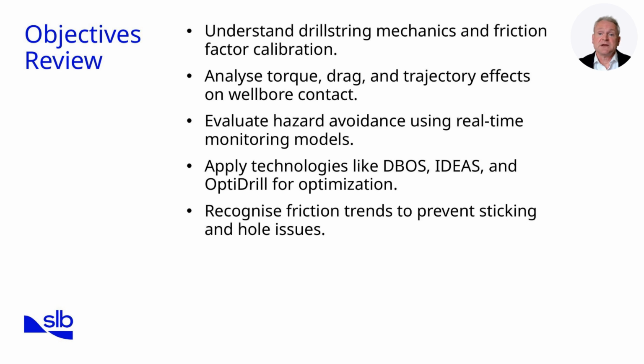Let's revisit the objectives we set out at the start of this sub-module and review how we've addressed each of them. Our first objective was to understand how drag and torque measurements are monitored, calibrated, and used to predict performance in future wells. We achieved this by looking at field data calibration, torque and drag modelling, and how broomstick plots are applied in practice.